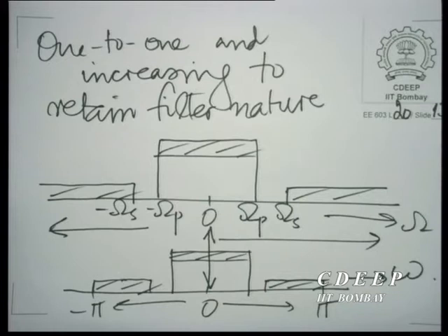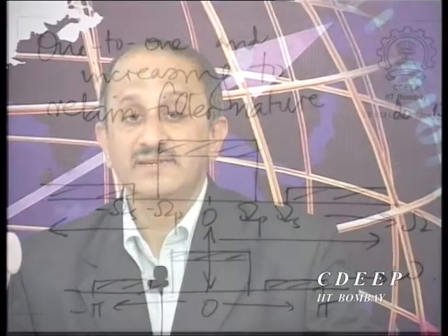We also have a hint from where to begin. The transformation must essentially be an approximation of the derivative operator in terms of shifts. And what simpler example of a derivative approximation can we have than to subtract the past sample from the current sample. You see, what is a derivative? A derivative is essentially a rate of change, and the smallest unit of time on which we can measure change in this discrete system is one sample time. So, if we look at the change in one sample time, we have an approximation to the derivative.